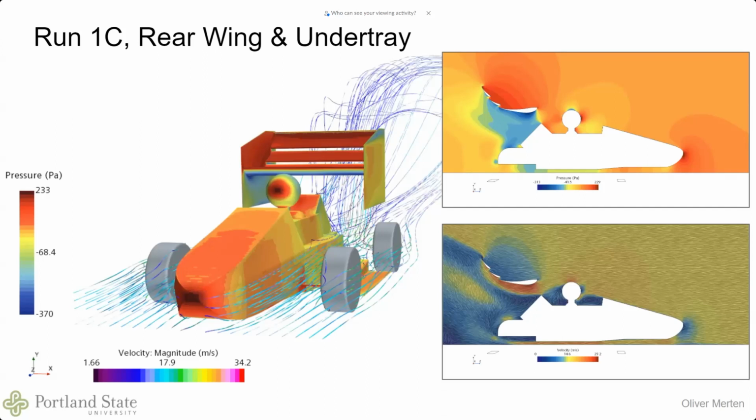I'm not a race car driver, but there's also the benefit of the pressure behind the vehicle. So in this upper right corner plot, there's lower pressure behind the vehicle. If you're drafting on a bicycle, or if you're really driving dangerously behind a semi at highway speeds, right on the end of a semi, you actually get pushed along because the airflow way behind has a higher pressure, and the airflow in front between you and the vehicle in front has a lower pressure.